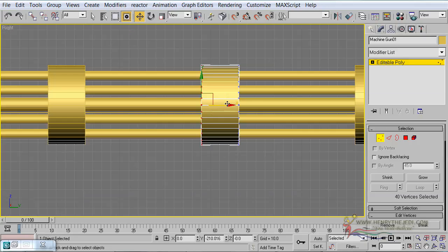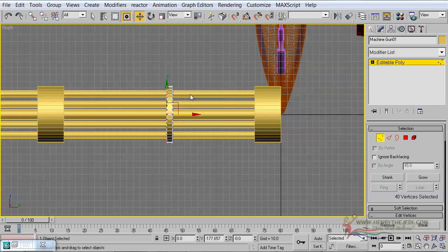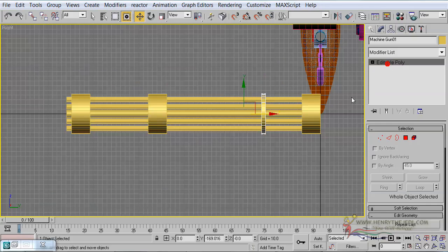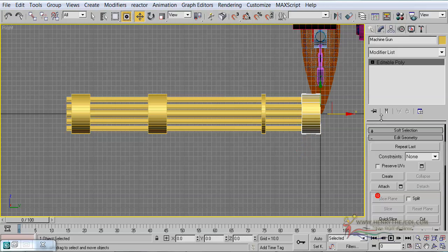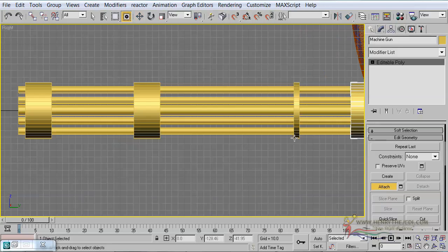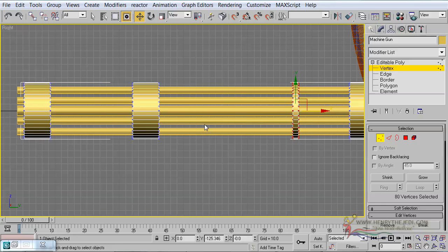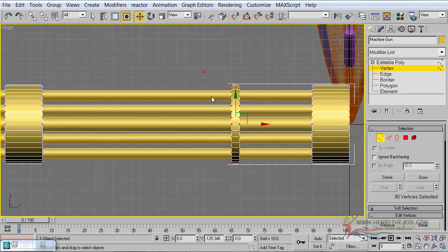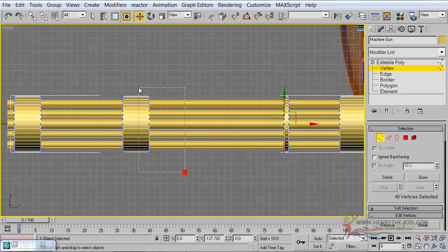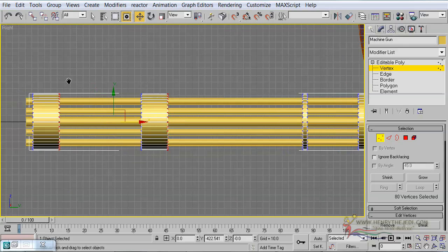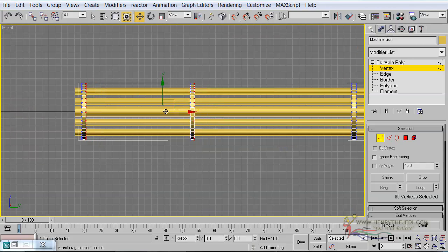and we simply want to squash down the polygons here, and they should be closer to the ones at the beginning. In fact, let's select this guy and attach the rest of these polygons to it. Okay, because after all they are still the same object. Back to vertices mode, and I think this one here needs to be scaled down a bit more. Select those ones also and move them, of course, to be much closer, as you can see.